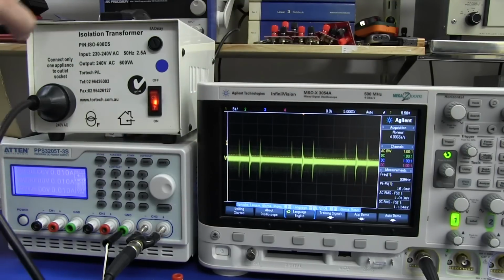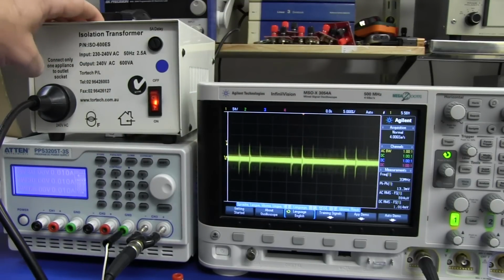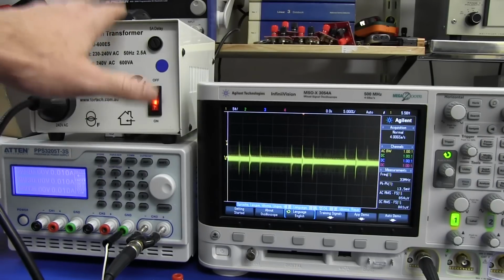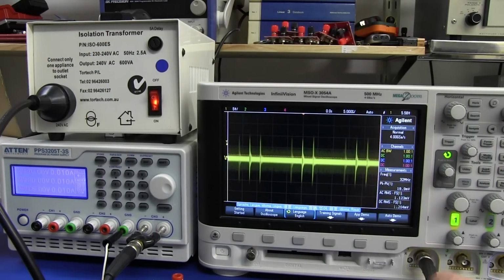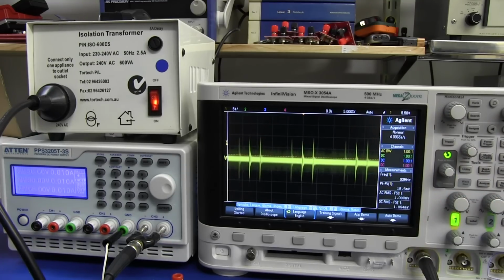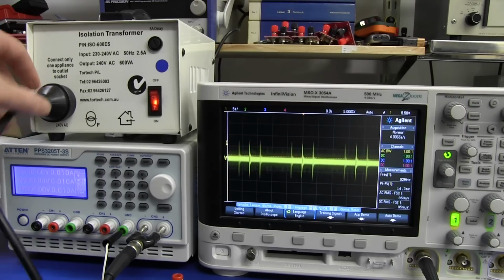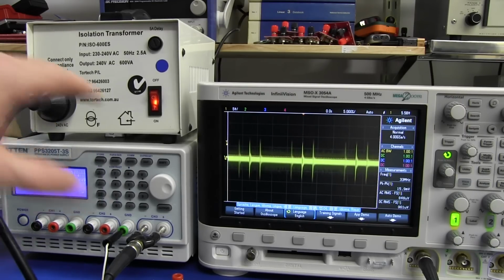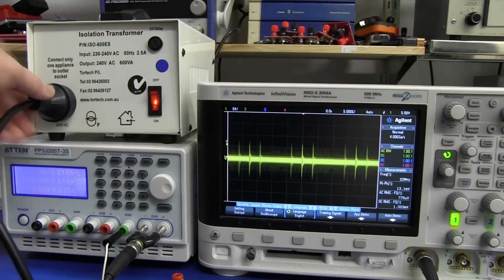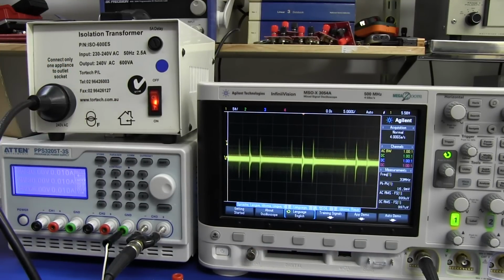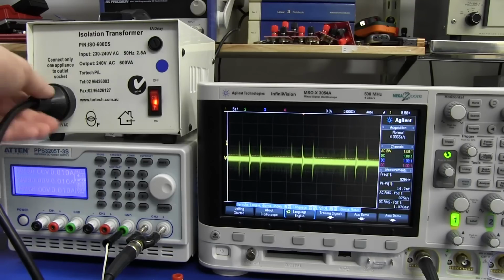Now, what I've got is this isolation transformer here, and this physically removes the mains earth and isolates this, so it effectively turns this oscilloscope into a floating instrument. It's not mains earth referenced anymore, so now you can use your scope probe to probe your circuits so you don't blow them up, etc. But because it physically removes the earth on this thing, it's not recommended to do this. By the way, usually you power your product through this thing and not your scope, or you use a proper high voltage probe. That's for a different video.